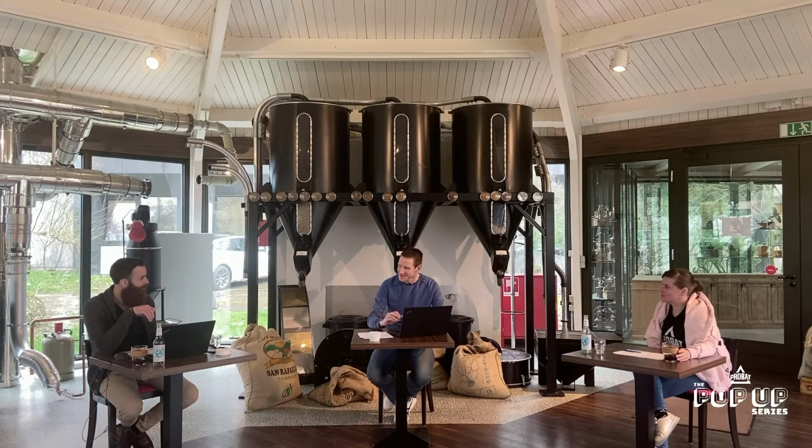So it depends on the desired roasting time. If you are looking for a very quick roasting time, let's say 8.5 minutes, and then coffee out, it might be that you have to reduce the nominal batch capacity, so not 12 but 10 in a P12. But usually the roasters are designed to cope with the nominal batch capacity that we name.